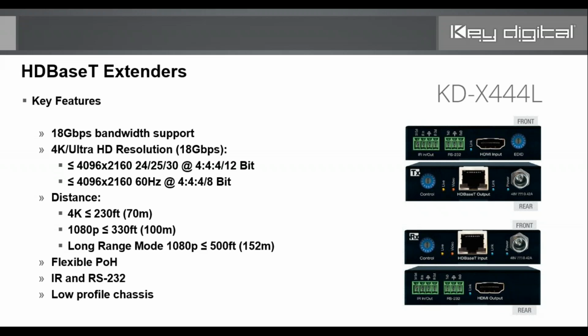And this product, KDX444L, supports resolutions and video signals with up to 18 gigabits per second bandwidth. This is something that was not previously possible only a year ago. The L part of the model number is for long, because this product uses a superior chipset. It could give you 4K at up to 230 feet, 70 meters, 1080p up to 330 feet, 100 meters, or